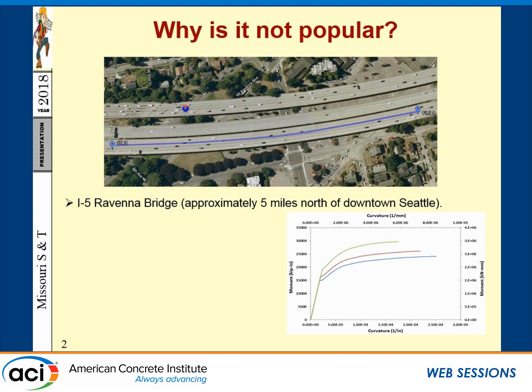So this is the effect of the axial load. Of course, as you increase your axial load, your strength increases, but it comes at the price of ductility. So you lose ductility as you move from low axial load to high axial load. However, in any case, your curvature ductility is quite small.